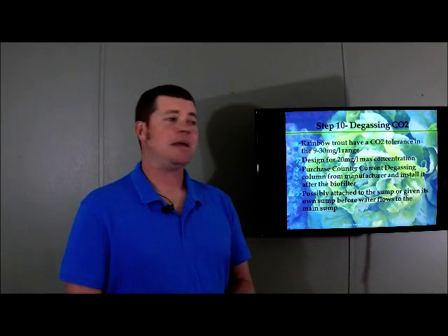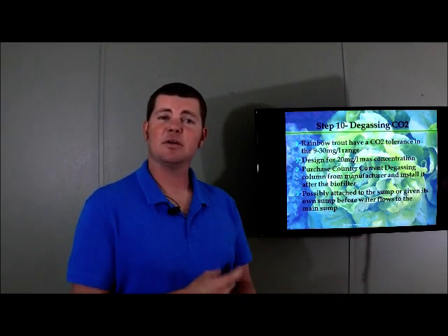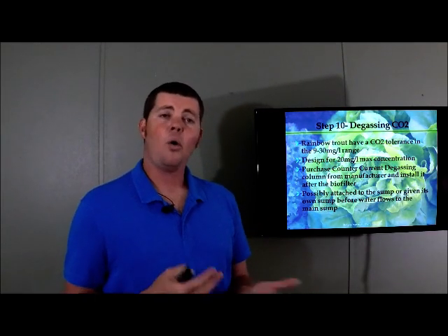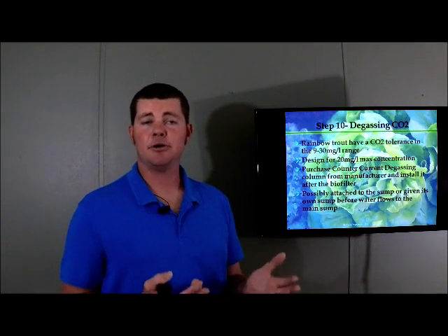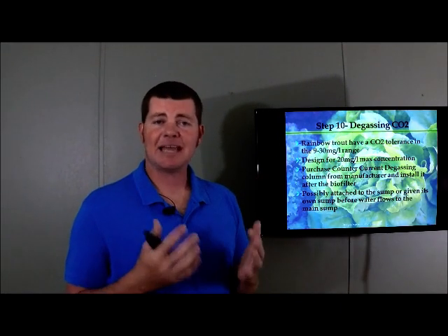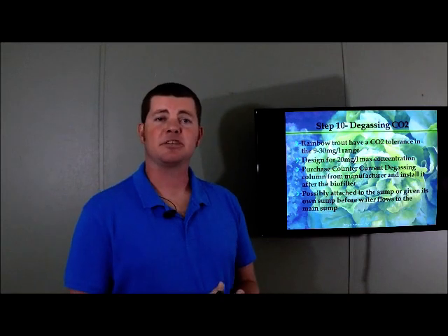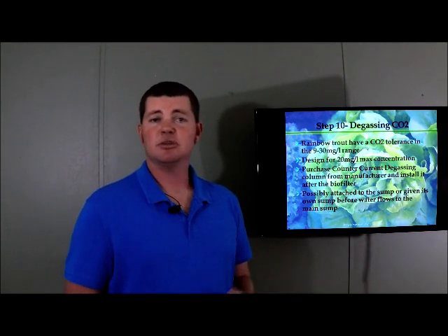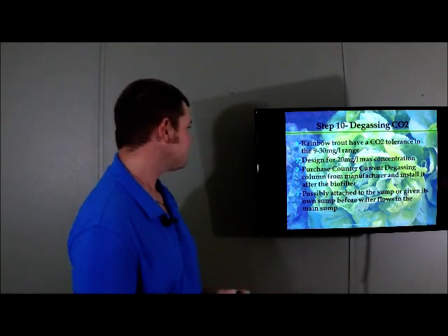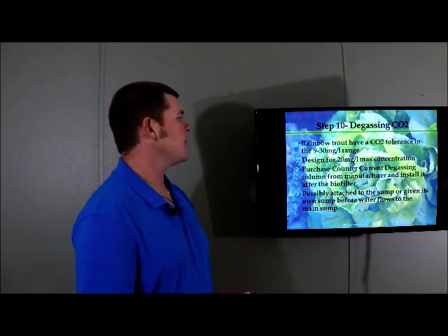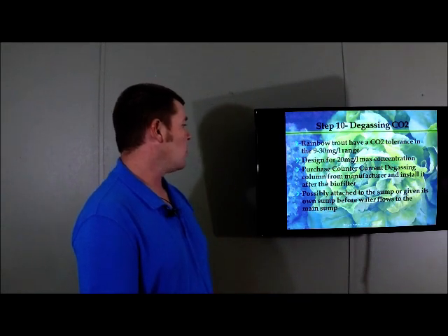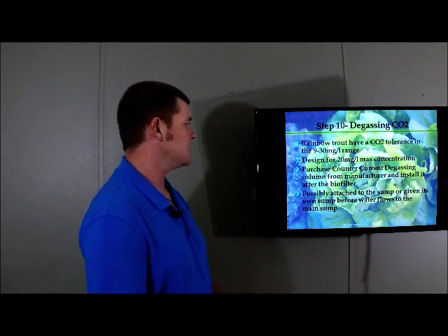So depending on the layout, you could have the water flow from the biofilter into the top of the degassing column, trickle through that and land in the sump, or you can build a small sump underneath the degassing column simply to catch the water from that, and then the water would be transferred to the main sump from that small sump. So it would just be a small sump to catch the water if you didn't want to house this over the actual sump. Okay. Purchase that from a manufacturer and install it.